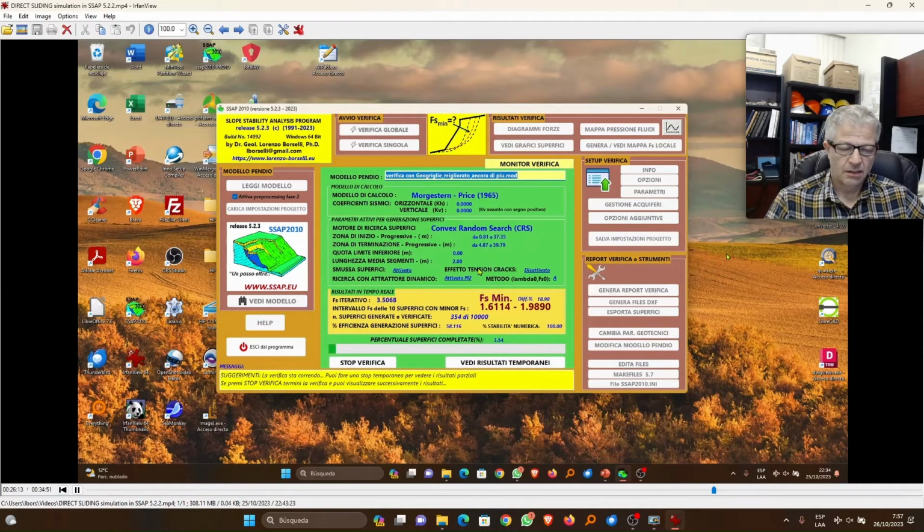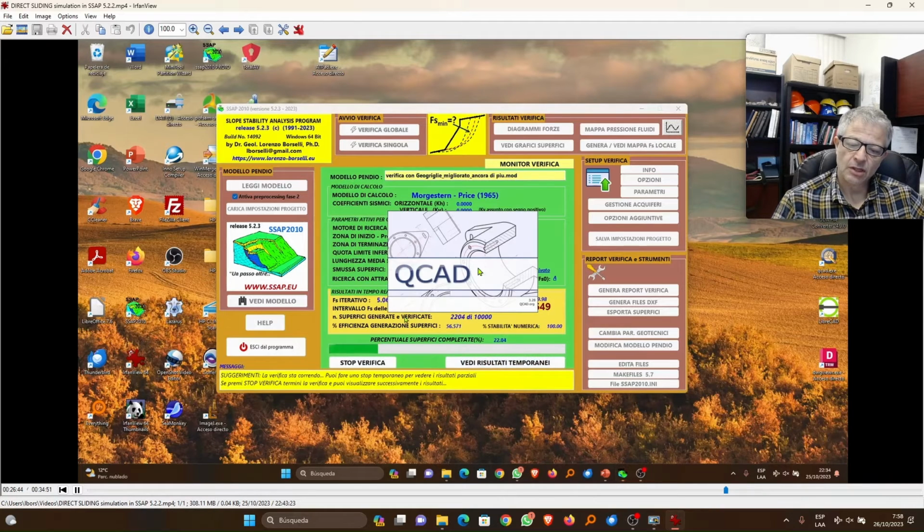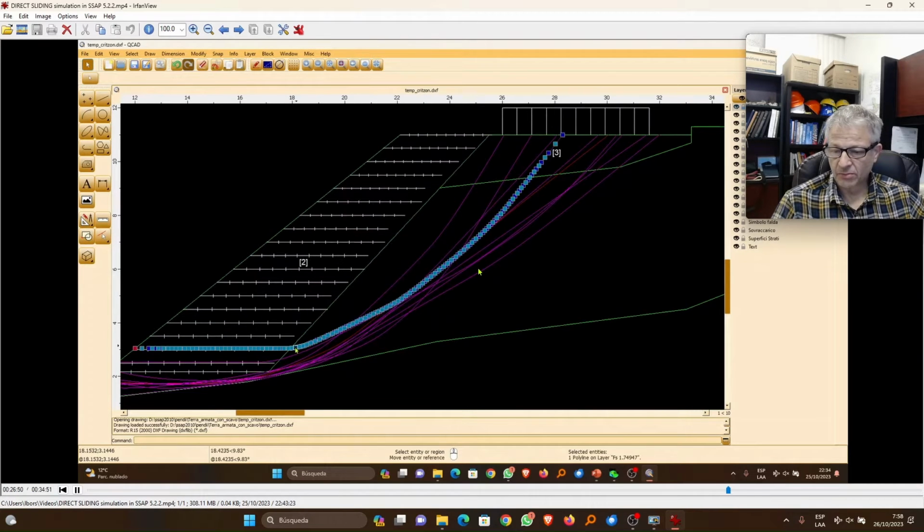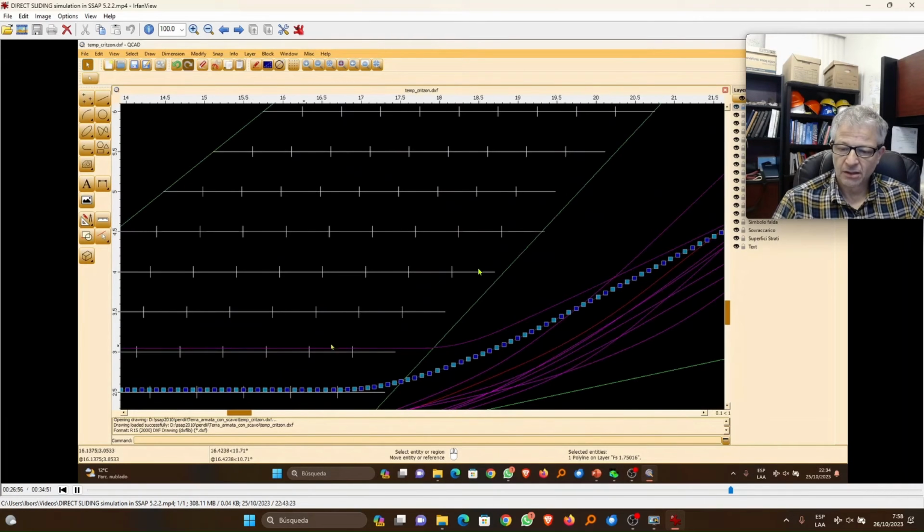This engine is extremely fast with respect to the others, but you can see that even if we arrive at the same value, the safety factor is not as low as before, because in this case, even if the surface passes very close to the interface between the geogrids and the soil, or inside the interface, we don't identify it so easily.